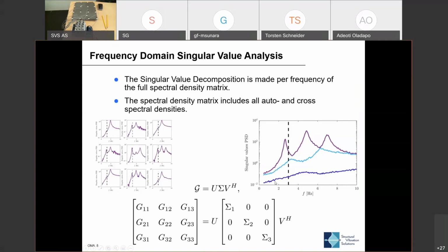Instead of having the power of the square of the number of channels to monitor in the spectral density domain, we are now back at actually only looking at the same number of singular value lines as we have measurement channels. So that's a really nice simplification of the thing, and still you see everything in a single diagram. Let's try and see.